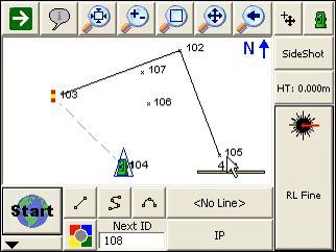One more thing, there's no limit on the amount of points you can resect to. Definitely the more you have, the more accurate of a position is going to be computed. FieldGenius uses a true least squares for the solution. And that's about all.